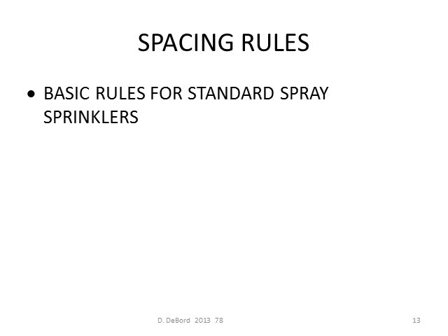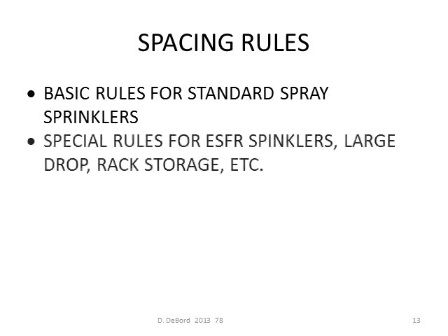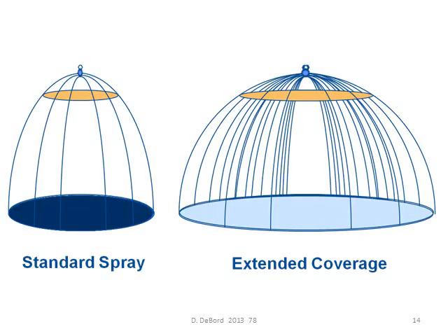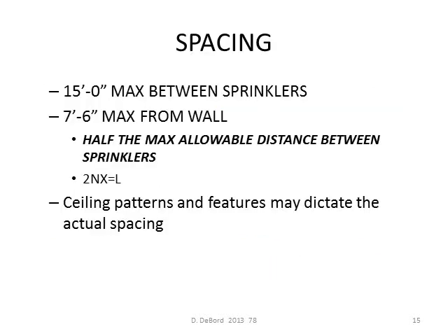Basic rules for standard spray sprinklers, and we'll look at some special rules for ESFR sprinklers, etc. You can see there's a big difference between a standard spray and an extended coverage sprinkler. It covers a lot more. They're a lot bigger, and they put out a lot more water. But it's for special storage applications.